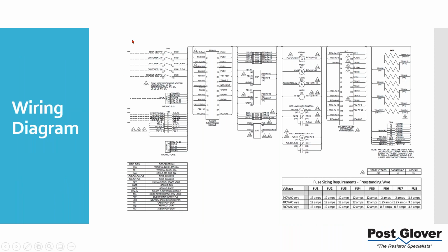I will say we have 2 different diagrams I want to show you. This is what I would call a point-to-point wiring diagram. Very good for checking wires. Very good, just make sure all the wires are in the right place, and usually it corresponds to the label. Essentially, it tells you where the wire is going. So if you see here the wire coming out of your terminal block, it's going to appear. This wire is going to your CPT, so you know where it's going. So you can check that, and that's how you can check point to point fairly simply.